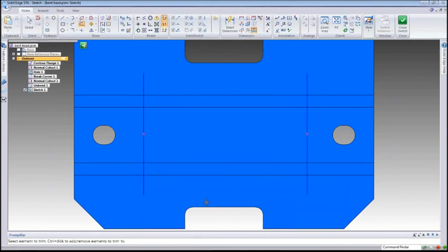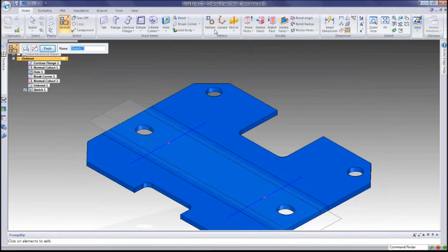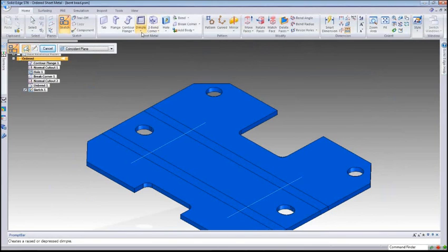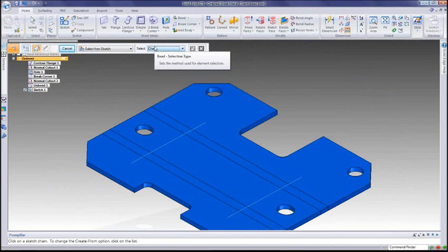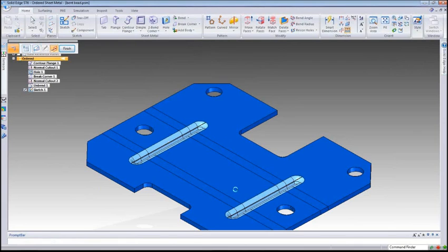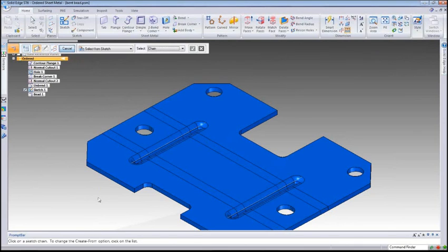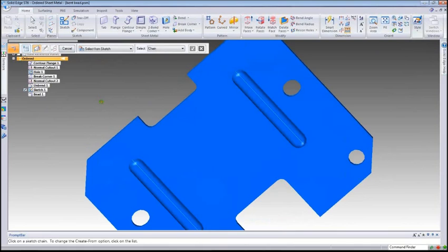And then what I'm going to do is I'm going to cheat a little bit, and I'm just going to get rid of these 2 lines here. I'm going to go ahead and close my sketch out. I've got 2 lines here. Why do I have 2 lines? Because what I'm about to do is add in a nice bead. This bead looks cool. So what I want to do is say, hey, I'd like to select from sketch. I want to select that one, and I want to select that one. And I'd like for that bead to be pointed down. And sure enough, it throws a bead in there. Everybody's seen these beads. They're pretty darn cool.